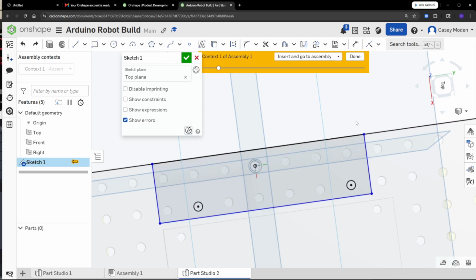I'm actually going to go back in time because I had those little dots left over. I'm going to click here, and I want it to be just right here, and I want to define how thick this is, not let the existing geometry define that for me. So for this distance, I'm going to make this 1/8 of an inch. That's a pretty common thickness for this. I'm going to say 1.25 for that.